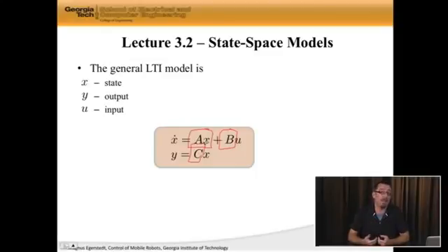And as we will see later on, sometimes we may not have enough control authority, for instance, to make the system do what we want, meaning our B matrix is too measly, which means that we have to buy a better B matrix, maybe buy a new actuator or so. But at the end of the day, a system like this is influenced by our control signal, u, that's the input, and out comes y, which is ultimately the thing we can see. We can typically not see x, but we can see y, because that's what our sensors are measuring.